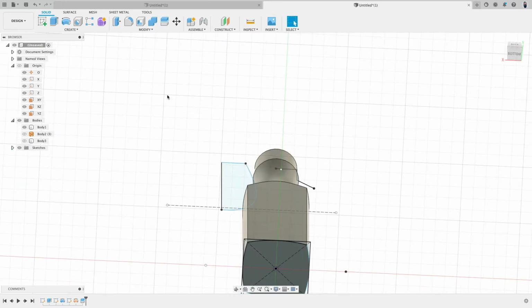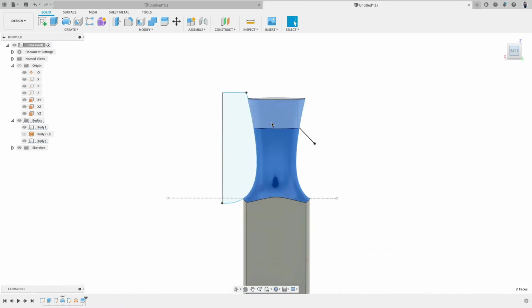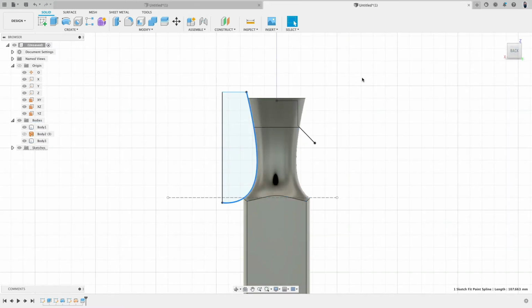Cool. It separated it. So why do we do it this way? Very easy. You see this surface flows perfectly into this surface. This is also why we make one curve and not two curves. It's about simplicity and also making sure our surfaces are perfect. I could have drawn this curve in one and a second and with a lot of careful manipulation made the flow equal, but that is nearly impossible.